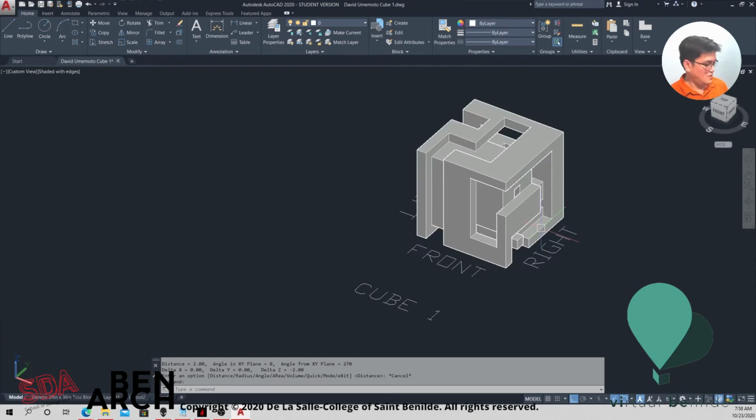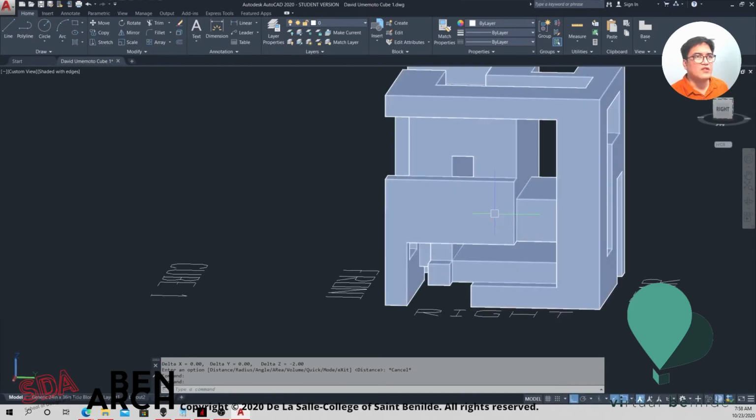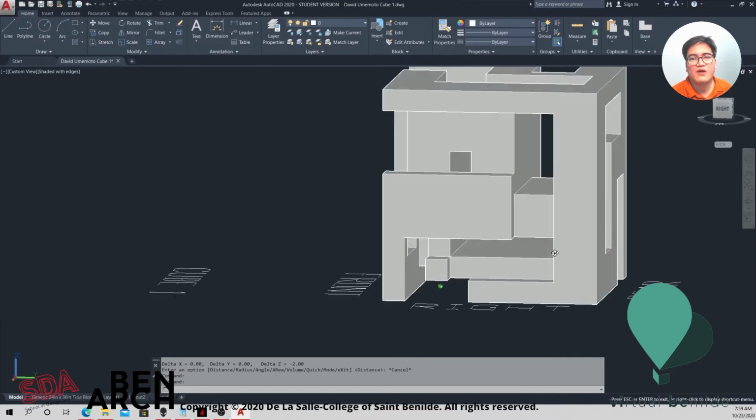Now some of you would be asking also, what floor levels would you want these to be? Of course, do consider that there's going to be a floor slab and then the ceiling underneath if you're doing the second floor. Therefore, the clearance of any ceiling would actually be a minimum of 2.1, but that's not ideal. Ideally, a good ceiling would be roughly about 2.4. Standard is 2.7. So do consider all of those.